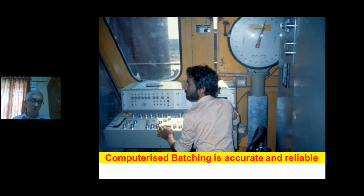It also had fully automatic operation. If you have fed in the computer that you want 5 cubic meters of concrete into the transit mixer below, one after another, the batching plant will batch 1 cubic meter 5 times and give you the complete content of the transit mixer of 5 cubic meters. So that was fully automatic mode.